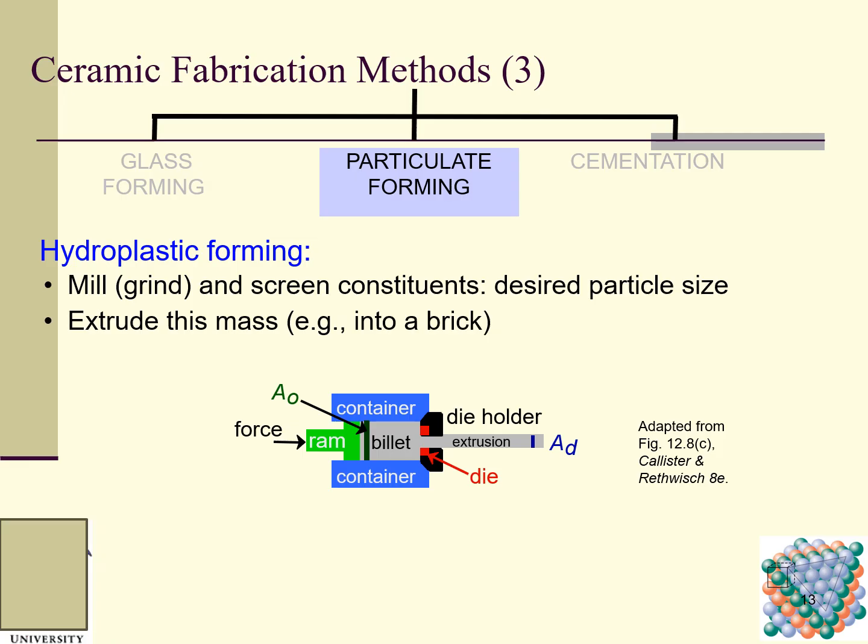And then we talk about particulate forming and hydroplastic forming. Mill, grind and screen the constituents to the desired particle size, and extrude this mass into a brick.